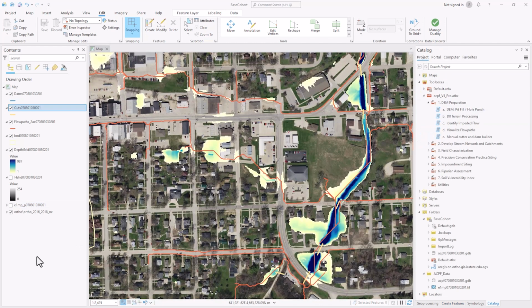When it comes to cities, fewer cuts will be needed. There are many reasons for this. One is that it's not agriculture, so the flow within a city is not going to affect our results. Another is that a lot of the impeded flow does not allow for cuts to be effective. LiDAR will return off of buildings and trees, so elevation change within a city does not allow for proper flow.